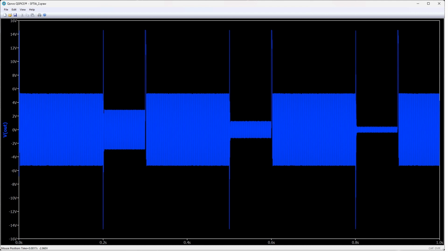We can identify 3 regions where the gain is reduced by the lower feedback resistance that is switched in, and we can see 4 places where the gain is at the level caused by the 100 gigohm resistor. Note that there is a transient in the signal when the switches are turned on or off. Charge injection is causing the output to spike to the power rails. This problem may not be an issue for some applications and will likely increase cost and complexity to solve.